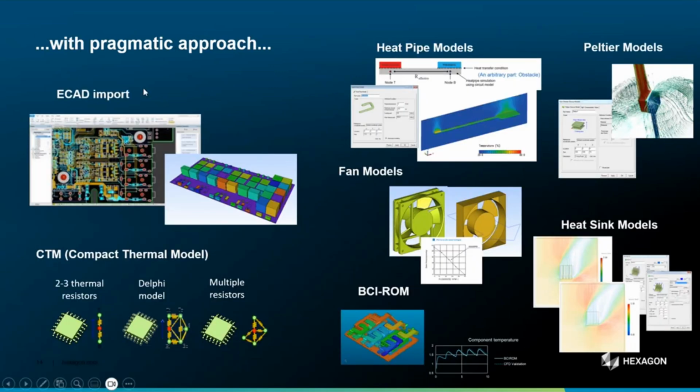But in electronics, we are also dealing with ECAD, for example, geometries that are coming from the electronic world. We are able to import them directly. For the components' behavior, because these guys will be dissipating some heat, we want to catch the thermal behavior of the component. We are not interested in what is inside the component. We are interested in the way it will thermally behave. So we can represent them with very smart modelization.